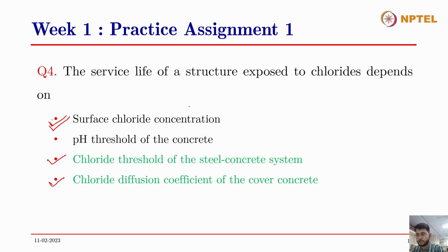The surface chloride concentration might be high, but if the diffusion is slow and the chloride concentration inside the concrete is sufficiently below the chloride threshold value, then essentially it will not affect the service life of the structure. That's what I want to mention.